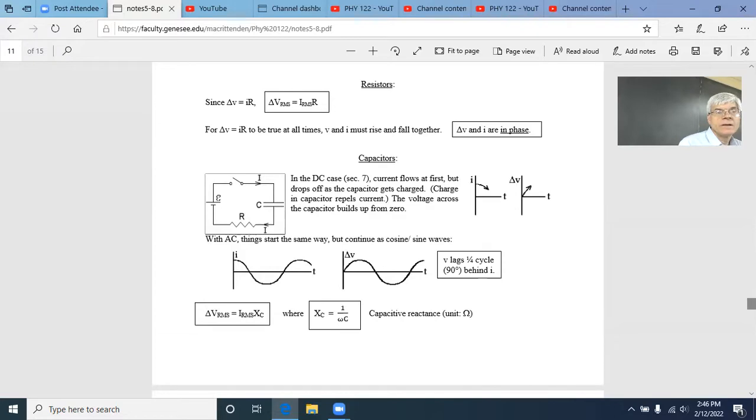Ohm's law is for direct current, or at least that's the way it's been presented so far. You can't necessarily assume that everything I said about direct current carries over to AC. For example, Kirchhoff's loop rule does not work with RMS currents, because AC effective currents are always positive. So if you follow a closed loop, how are you going to get a bunch of positive numbers to add up to zero? Okay, so the loop rule is for DC currents.